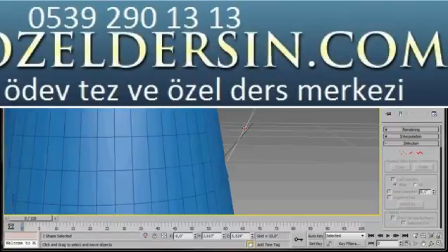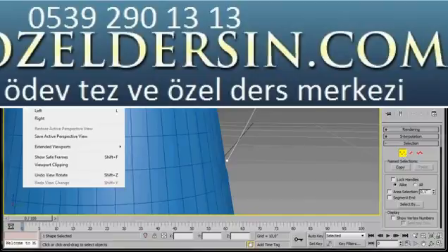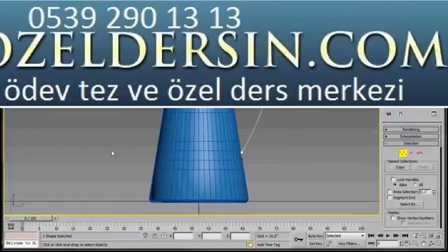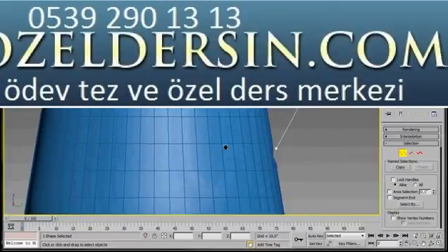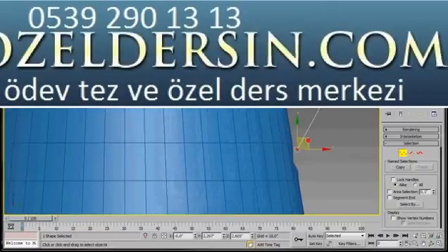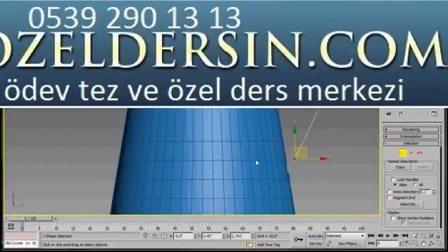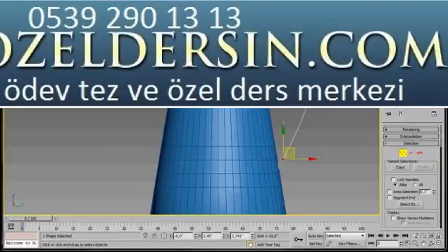Now we're going to select the line and the vertex mode, but I'm not going to move any vertices yet because I'm in the perspective viewport. Let's come over, click on the word perspective and choose the right viewport. Now let's zoom in here in the right viewport. I'm going to select my vertex and I'm just going to move it. Just drag it out of the way. It's only a trial. I can always come back and remove it if I have to. There, I think that distance there should be alright.